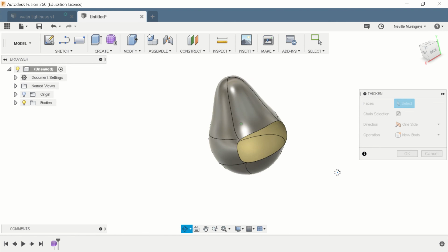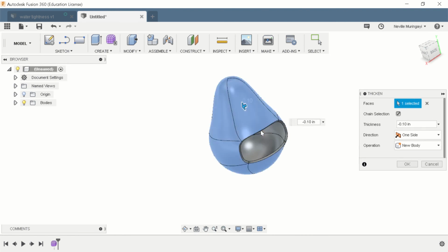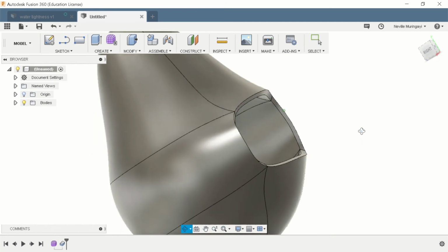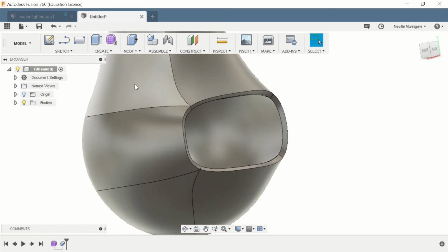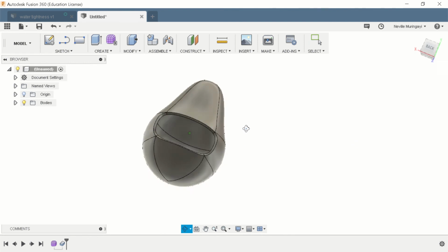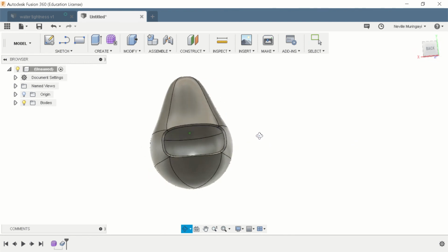All right. Then I'm going to click this object here, and I'm going to set it to 0.1, because if you try to do a little bit more than that, it won't define it perfectly, because it will go past the constraints of what it can handle in terms of our given shape. So I'm going to click OK, and as you can see, now we have a defined thickness all the way up and around. Basically, this whole object has a 0.1 thickness, and so if we try to 3D print something like this, it would actually be able to print it.